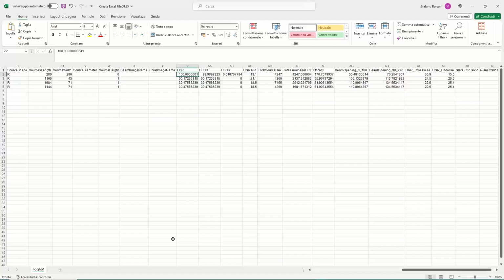So for example, if you change the flux of your luminaires, as we said before, because you are using a new LED generation, you have to change the flux. But if you want to keep the efficiency at 100%, so you want to consider absolute photometry, then you have to fix here the 100% value, so that the program will automatically modify the matrix in order to give at the end the same efficiency.